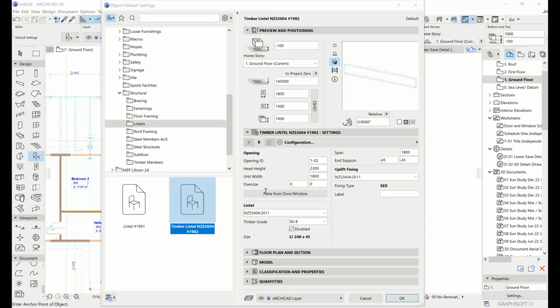When you draw a window in ArchiCAD, it's not an independent entity. It is part of the wall. It's an opening of the wall is what it's classified as, but it is definitely included. It is a piece of the wall. So you can't have a single window that is in multiple walls because it only ever can belong to one wall at once.